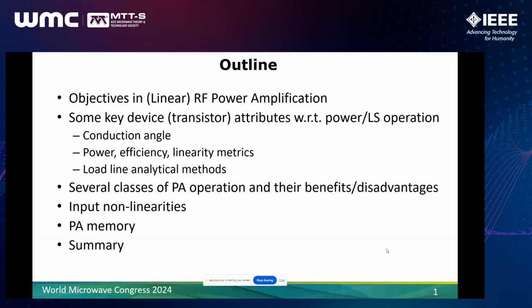We'll go through a few classes of PA operation, discuss their benefits, advantages, limitations, and disadvantages, and then delve into a couple of topics that are perhaps a little bit more complex. One of them being the input nonlinearities, so looking into the gate of the device, as the device is nonlinear, and we'll look at some of those effects.